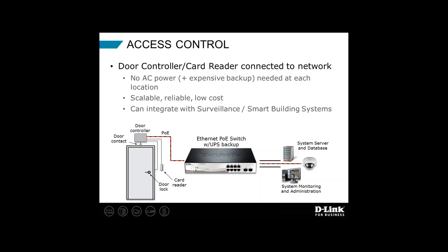With PoE powered door controllers and badge readers and card readers, all I have to do is run a LAN cable out to that area. And if I'm concerned about power failures, then I just use a UPS on my PoE switch. A fairly low cost UPS on my PoE switch in the event of a power failure keeps the PoE switch running, which in turn keeps the PoE running out to the doors so they continue to operate. And of course, systems like these door controllers and card readers typically can be integrated into other surveillance and smart building systems. So it really makes sense from a PoE perspective.